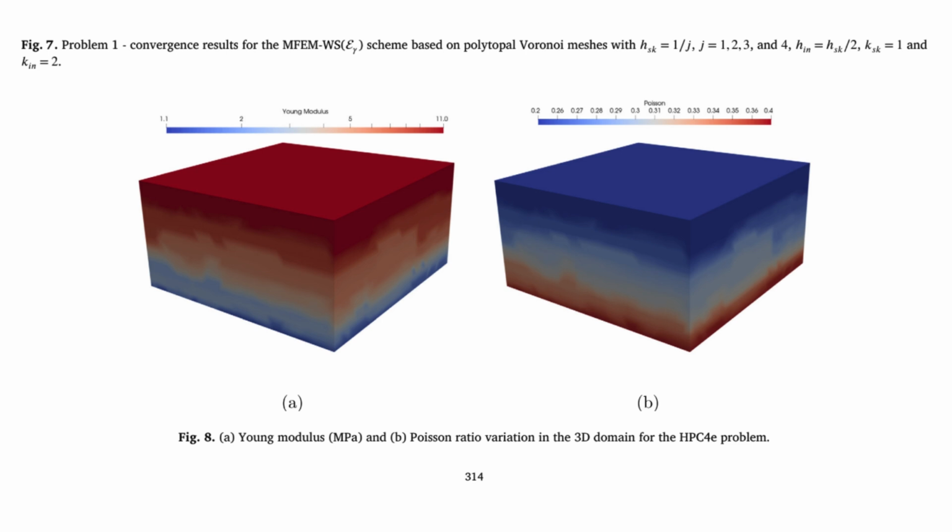So we've chopped up the problem. But just chopping isn't enough for speed, is it? You mentioned a secret weapon, static condensation. Yes, static condensation. That's really the engine driving the efficiency. It's a way to split the problem into a global part and many local parts. Global and local. How does that split work? What variables go where? We divide all the unknowns into primary variables and secondary variables. The primary ones are solved together in a single, relatively small global system. The secondary ones are handled locally inside each polyhedron.